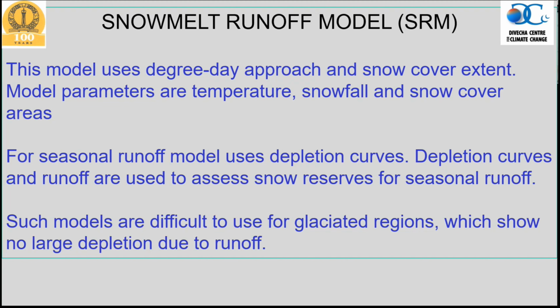If you look into hydrological models, whether you use the SWAT model or the WEAP model, particularly the SWAT model, snow cover comes through the land cover. What it means is that snow cover is considered as one of the parameters of the land cover. So the dynamic nature of snow cover cannot be accommodated into the model, and that is why people thought it was not giving very reliable results.